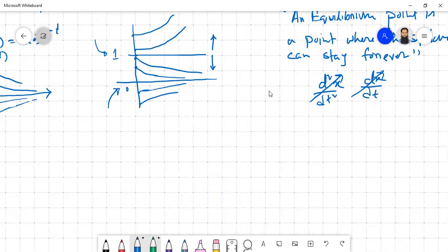Also, sometimes you can have some function which involves your input together with the system state. They are called bounded external input systems. So in terms of state space, you can represent the system something like this, x u. They are bilinear systems actually. Sometimes, based on the value of u, your system can behave like a stable or converging system, or can behave like an unstable or divergent system.